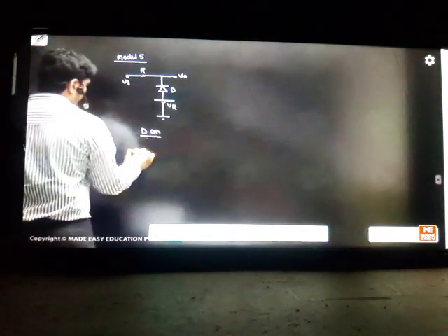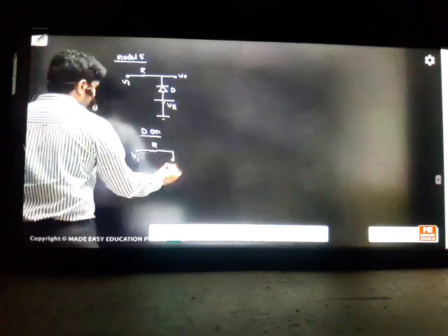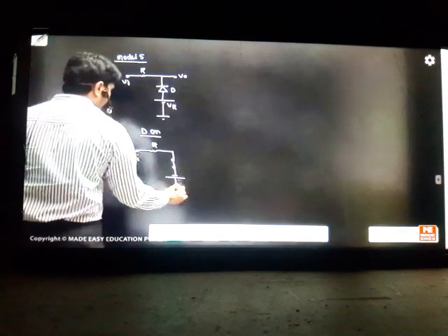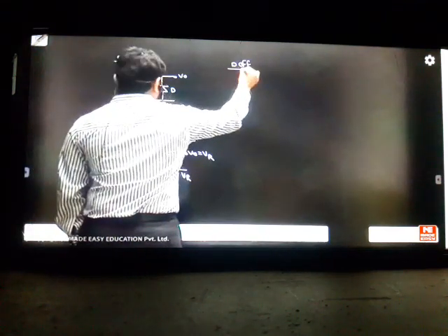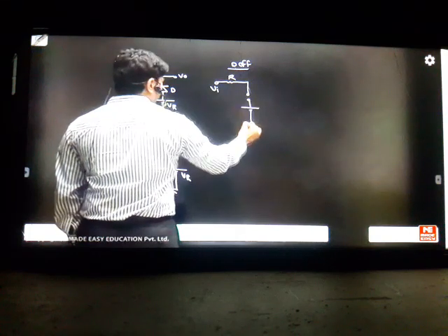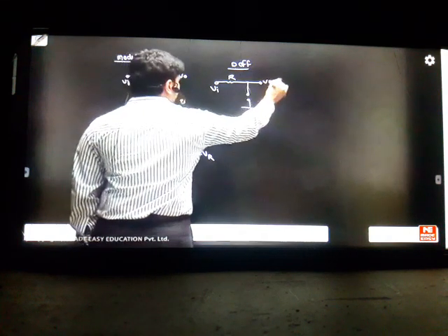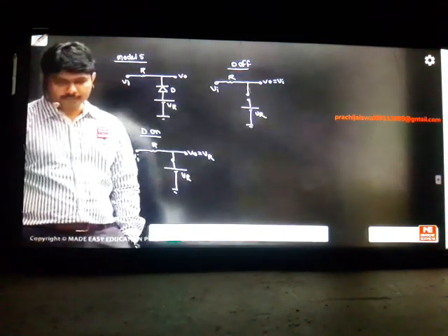So start doing it. When the diode is on, with resistor R and input VI, there is a short circuit with the positive battery, and the output is equal to VR. When the diode is off, we have the resistance R, this is VI, and we have an open circuit with the positive battery. This is your output; output is equal to input. We are getting these equations.